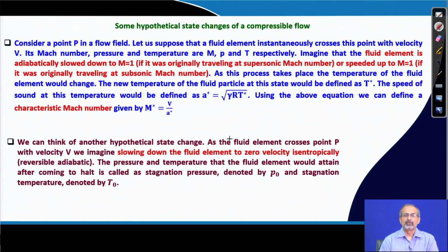We are trying to treat it as a hypothetical or imaginary case where we adiabatically slow down the fluid particle from a supersonic condition to a sonic condition if it is really moving supersonically, or we speed it up from a subsonic condition to a sonic condition. So, we are doing a mental exercise, basically, of hypothetically either slowing it down or speeding it up to the Mach 1 condition.